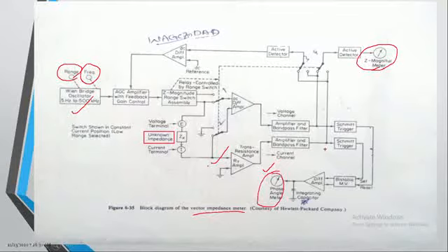Okay, so the magnitude gives the impedance of that particular element, and the phase difference gives clarity on whether the unknown component we are placing here is capacitive or inductive in nature. Let us go through the process of how exactly this vector impedance meter calculates the magnitude, that is the impedance, as well as the phase difference.